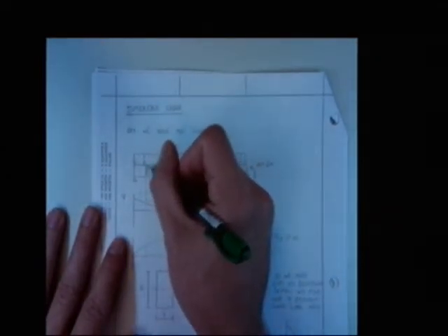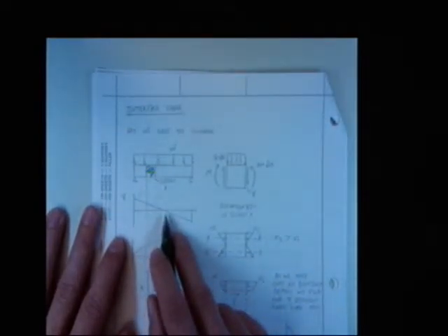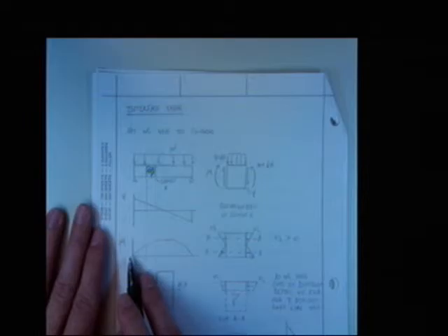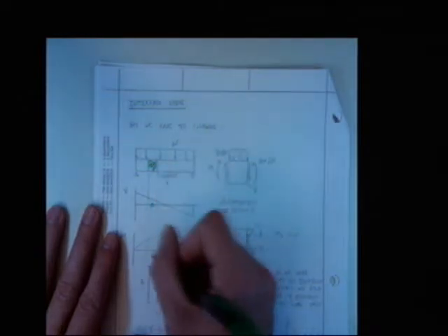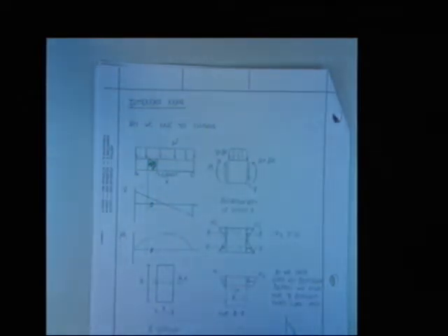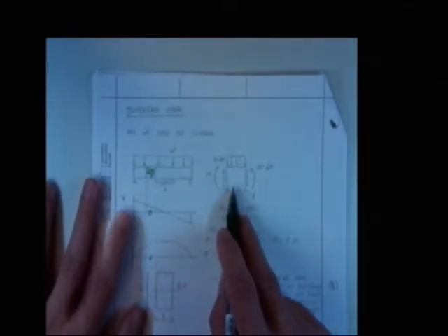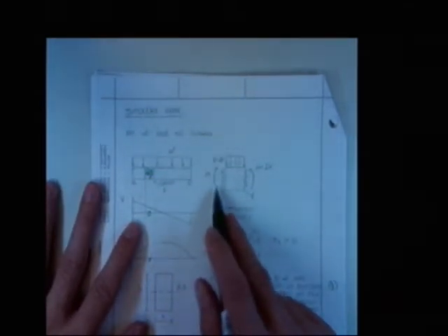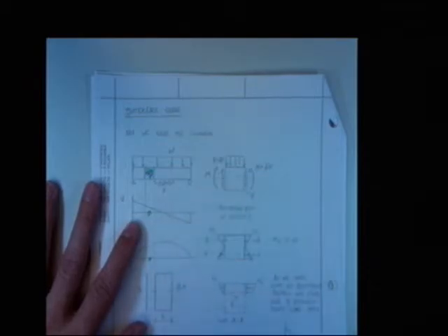talking about this element. So it's not in the dead center where shear is 0. It's not in the end where moment is low. I'm talking about an intermediate element. Okay? So this element's in here, in this zone. And if I take this element out and I look at the loads on it, I have moments on both sides, and I have shears on both sides.